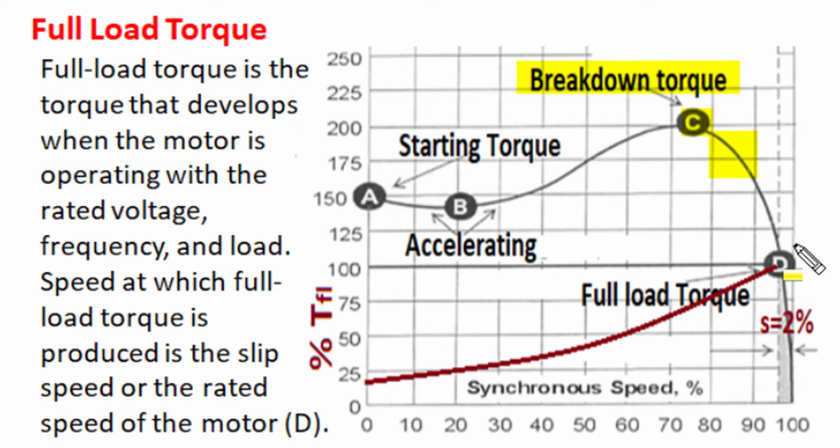At one particular speed position the decreasing motoring torque and increasing load torque intersect each other, and acceleration of the motor stops there, and the motor now continuously operates at this particular speed condition with rated voltage and rated frequency applied to the motor stator, and rated load connected to the motor shaft.